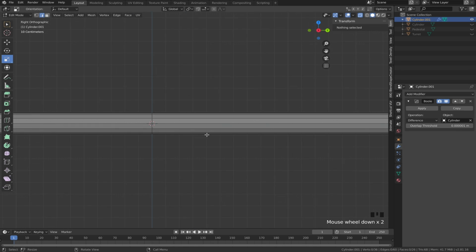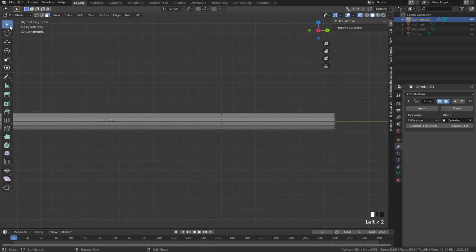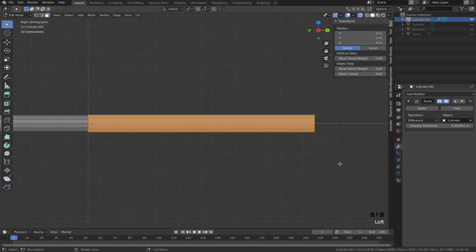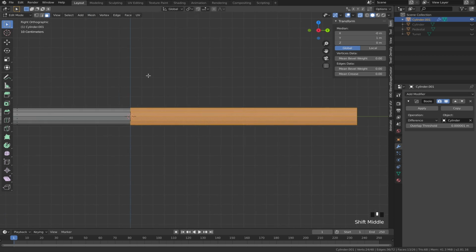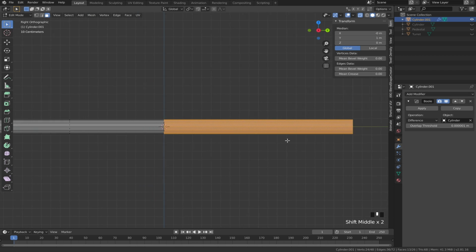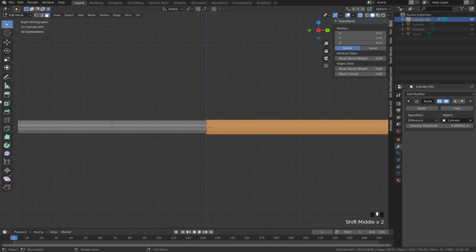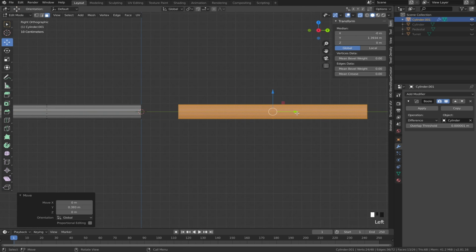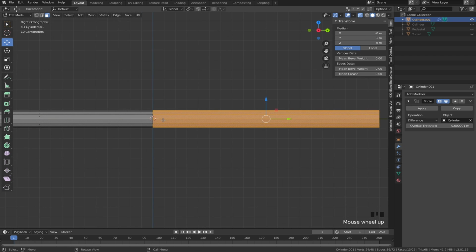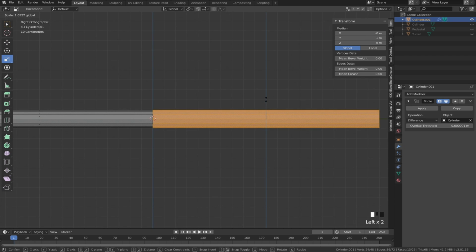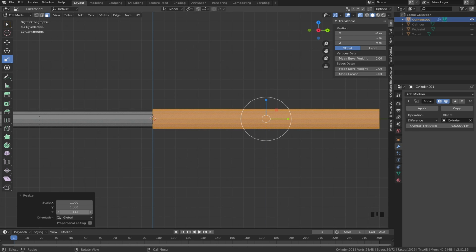So let's add something. Go here to face select and select these faces and press Y. Y separates these models that you selected from other pieces that are also existing on the model. So now if I pull this away, they're not connected. So I'll just change this just a little bit. So let's say flush.